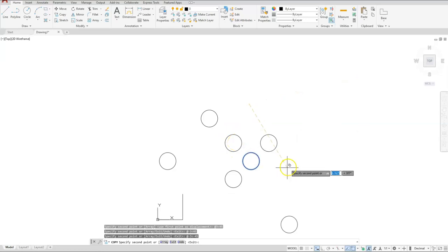So you can kind of confuse yourself. It's a lot easier just to type in the 3 and figure out what that angle is, which is 135, to get to that location. But you can use those negative values if you understand them. And like I said before, it's probably confusing. It's a lot easier just to type in 3 and use positive and negative angles, or use the negative distance and positive angles. But I would very rarely use negative values with a negative angle.